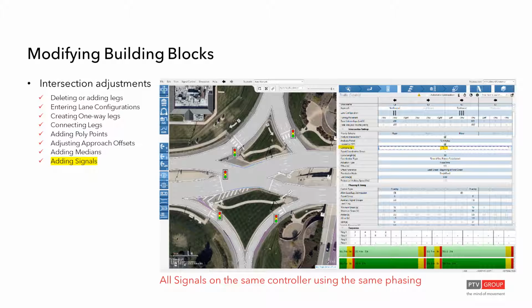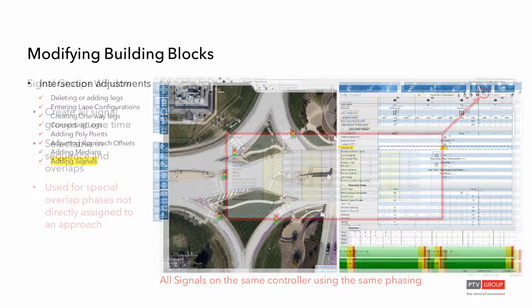And then tip number 2, which you may already know, is to create the poly points after you connect the legs. Some of you are probably laughing already about this, but it's really important to connect the legs first to your intersections and then create the poly points, or else you'll lose the poly points when you snap the legs together.